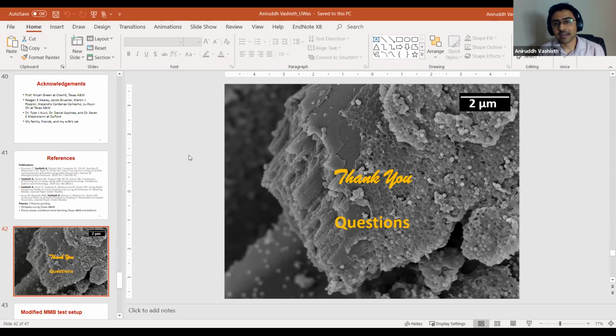That's a really good question. At least right now, all the adhesives that we have looked at have had some sort of nanofiller to increase the conductivity of the material. One thing that I tried out was I just looked at bifunctional epoxide and mixed it with a common curative, and they also heat because there are polar molecules in the epoxide chain. So you can get some heating that way also.